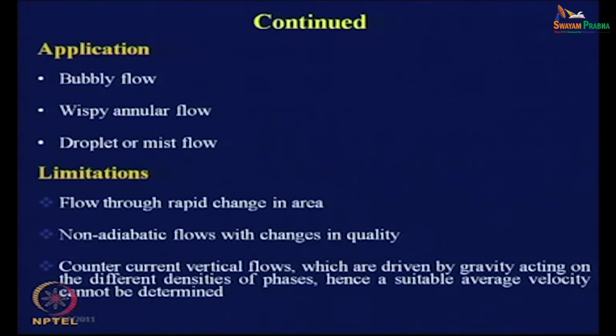Next, say bubbling in superheated liquid. Why? Because in this case we have to consider bubble nucleation, bubble growth and things like this. Then supercooled vapor, that is also condensing in a high velocity stream. These are the situations where this is inapplicable due to rapid acceleration and pressure changes, if you can note them down.